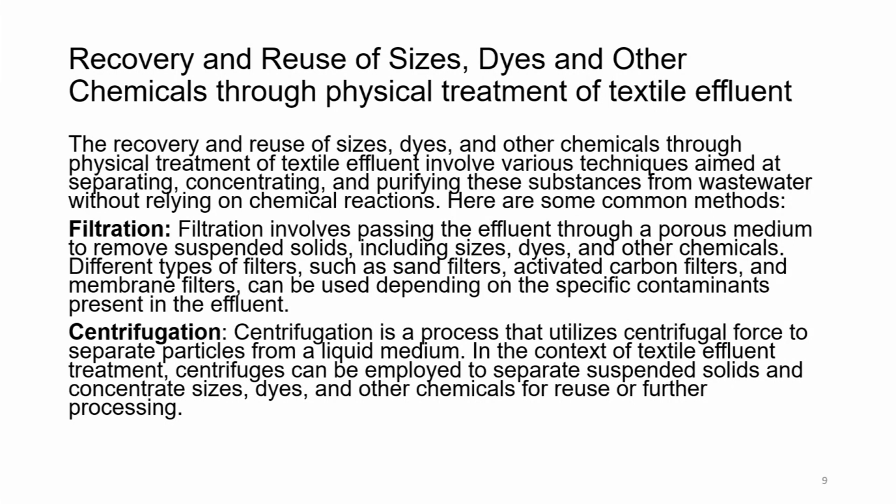Centrifugation. Centrifugation is a process that utilizes centrifugal force to separate particles from a liquid medium. In the context of textile effluent treatment, a centrifuge can be employed to separate suspended solids and concentrate sizes, dyes and other chemicals for reuse or further processing. So, this is very simple. By just applying the centrifugal force, the suspended particles settle down and that settled material is then isolated and reused.